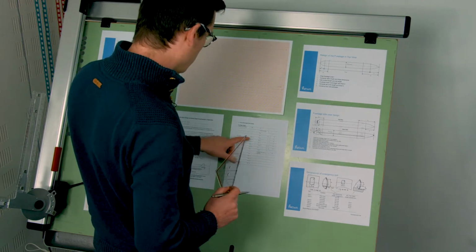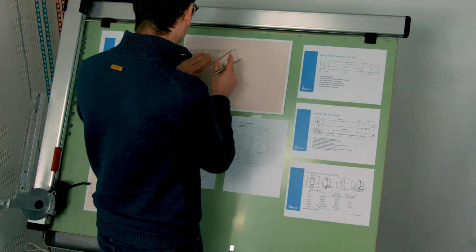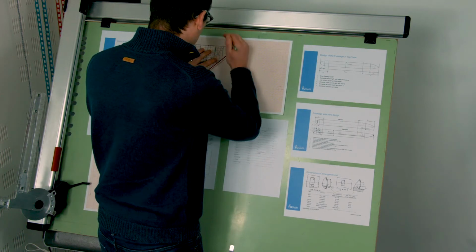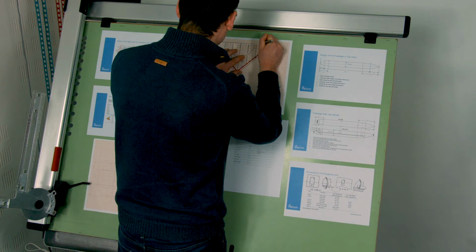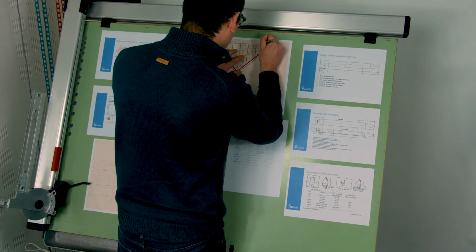I'm doing the same thing on the front side. So I look at my nose cone length. It's 5.1 meters. Brings me over here, rotating 1.7 centimeters up and down, and that gives me the first part, the straight part of the fuselage barrel. I'm going to be sure that that is correct. That's my first part of the fuselage barrel, which is going to be straight.